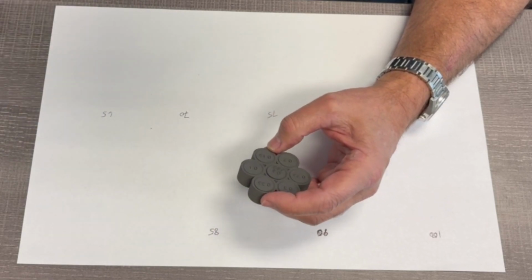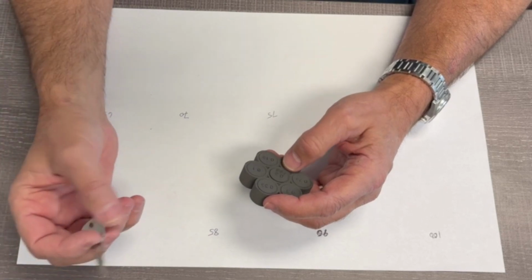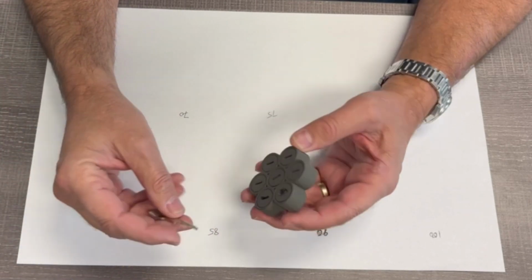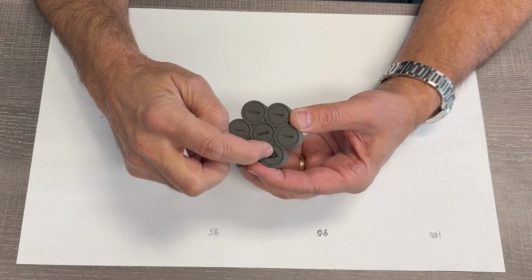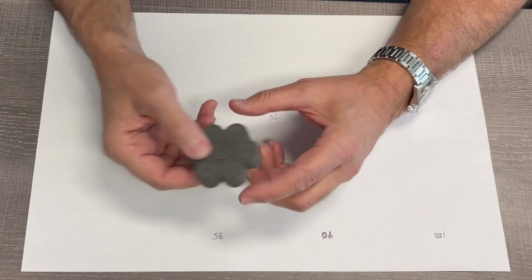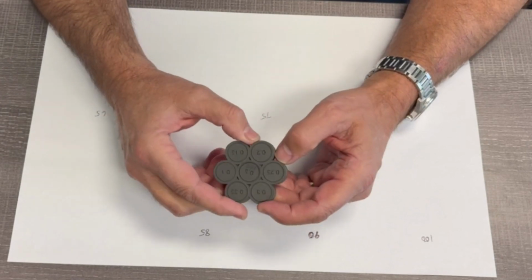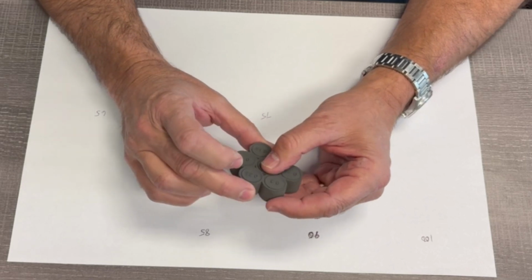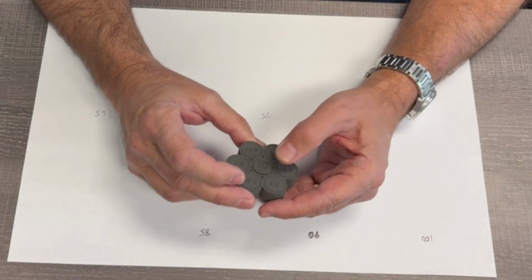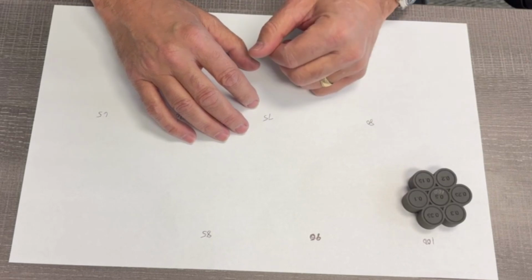Unfortunately, that's why, when I did the torture cube and my fidget cubes, things were getting tougher. I tried to move that 0.3. You can see I torqued on that pretty hard, and I couldn't get the 0.35. So at 100% default energy density, with all my other parameters set, the best I could do was maintain a 0.5 millimeter tolerance between functional parts.